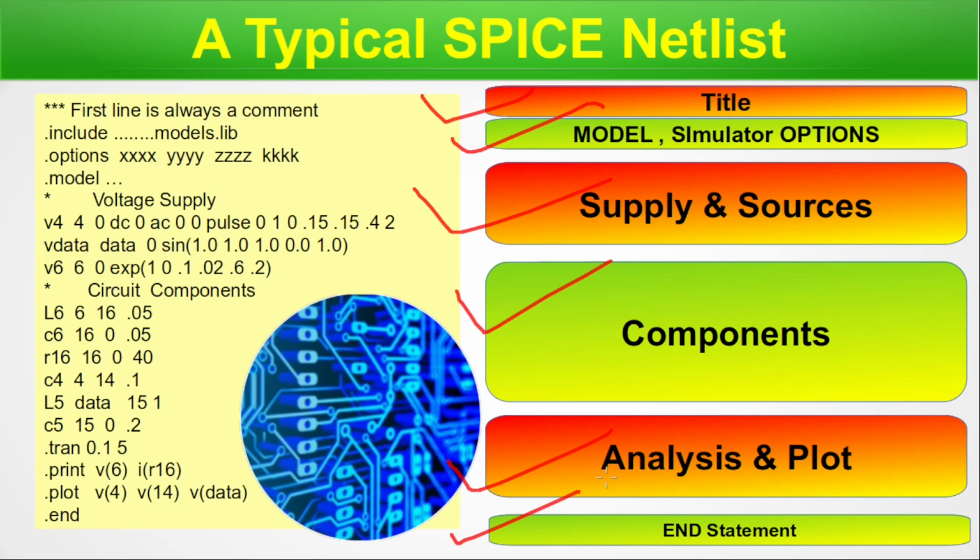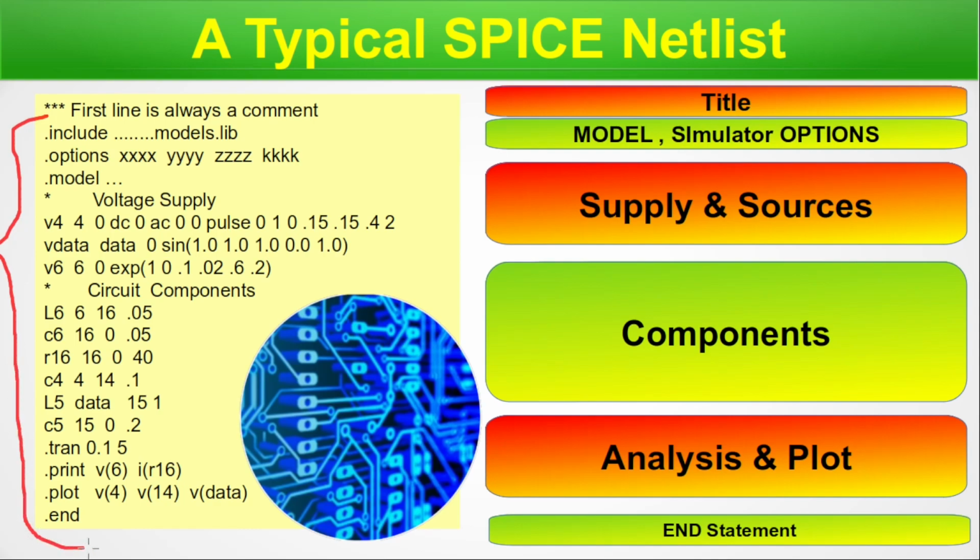Now, one thing I would like to say here, from one EDA vendor to another EDA vendor, there could be some changes inside this particular spice deck. They will be somehow similar. In addition, there could be some differences maybe in some of the area. While you are defining, there could be some of the commands that could be different from one vendor to another vendor. You have to be careful about that because there are several EDA vendors and all of them provide spice tools for the simulation.